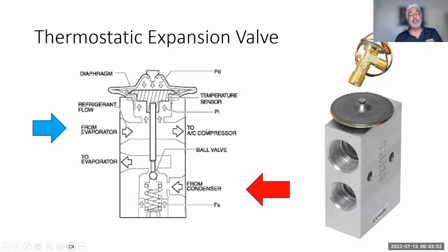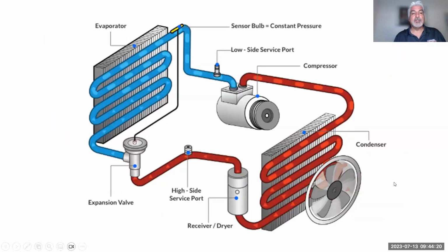So the rule is, if that compressor is grenaded, you need to ask yourself, why did it grenade? Was the clutch the issue, or did it ingest some liquid that destroyed it? That would mean that maybe the expansion valve might have been the cause. Actually, most likely it was the cause. So definitely pay attention to that. Okay. Any questions there? No questions? All right, good.